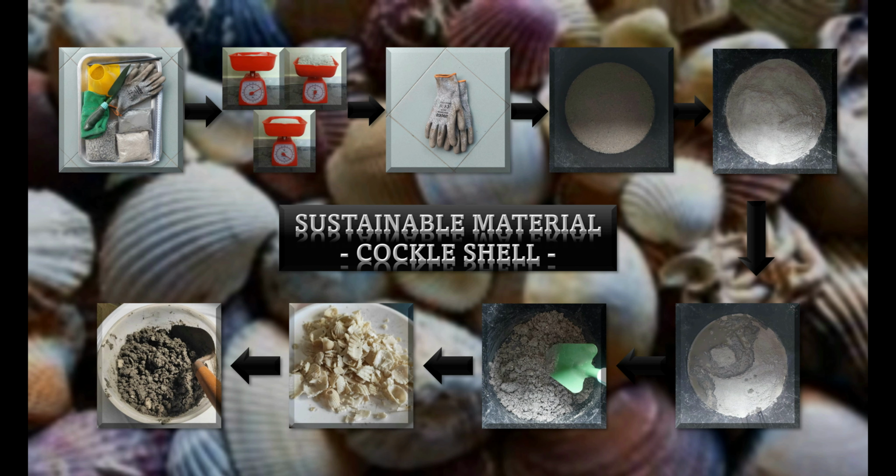And then for the coarse aggregate, about 10% of the coarse aggregate is replaced by seashell. So from 1.074 kilograms of coarse aggregate, about 100 grams is replaced by seashell, and then added into the mixture and mixed by turning over from side to center, while adding another 0.0595 kg of water until the concrete mix is uniform in color and consistency.